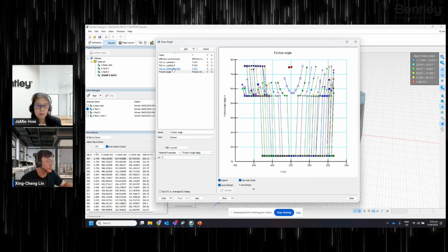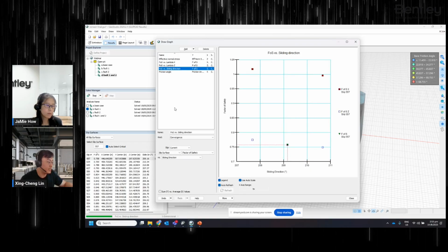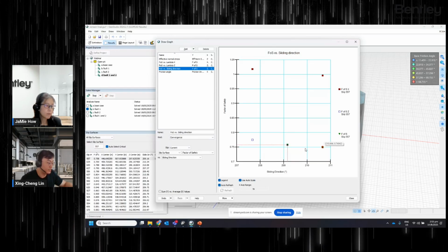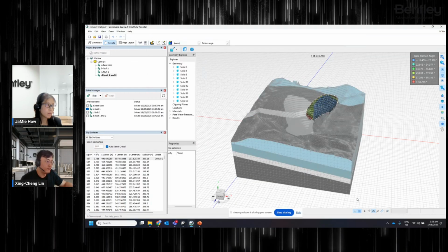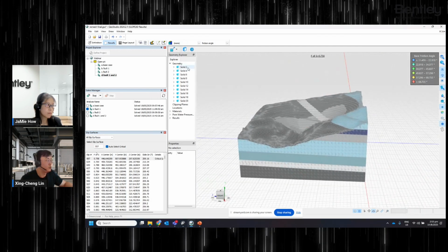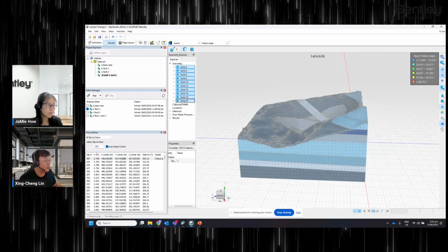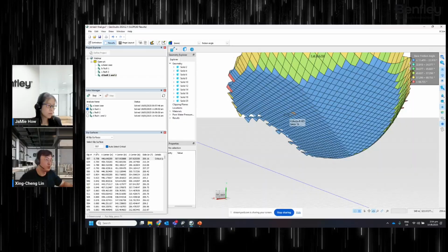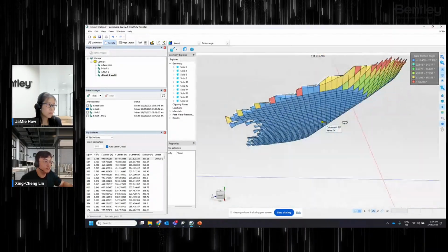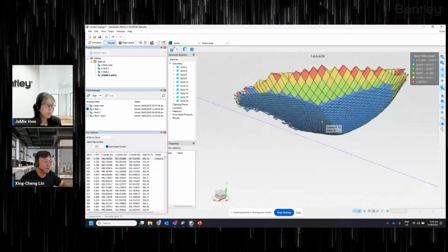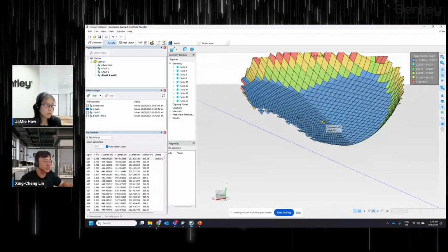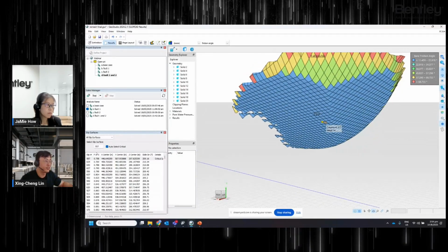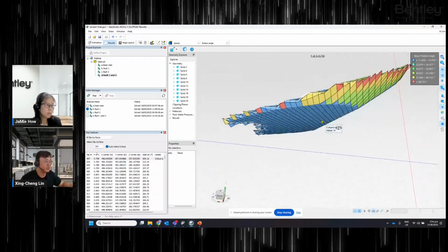And if I look at this factor of safety versus sliding directions, it's around 209. So that's the sliding direction. A lot of information is also available. So let's look at the slip surface shape for case number D. Clearly when two planes add together, we get this kind of biplanar or bilinear shape at the base, with the material highlighted in blue, the weak material color with a friction angle of 14 degrees. So this is the slip surface shape.